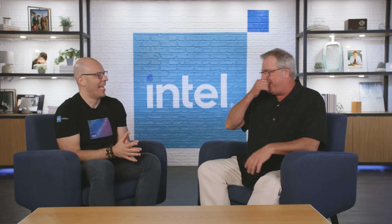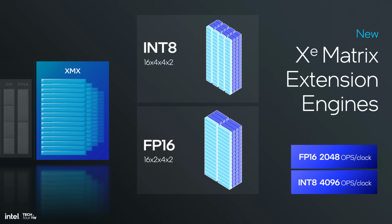AI. Yeah, XMX is our architecture that accelerates matrix multiplication. And it's built around a systolic array, which is a fairly complex thing, but think of it as a way to cache computations so that you can do these big matrix computations without writing back to memory a lot. So you can keep all that stuff local as you're iterating across these large matrices. And that is going to dramatically accelerate the performance on GPUs for integrated, for AI.